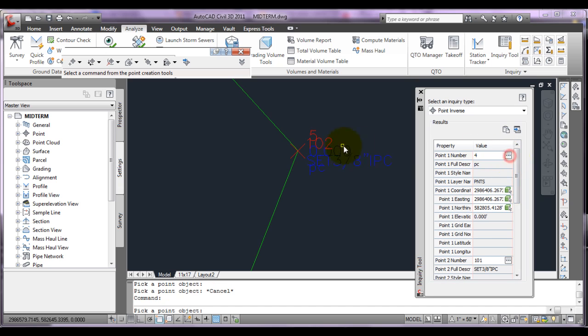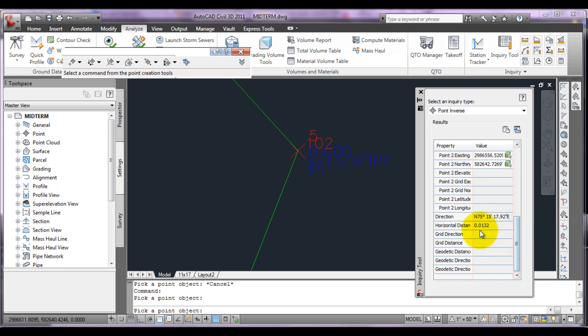And the reason why I do this is to make sure that there's a check and balance on that point set in the field. Make sure that they set it within your allowable standards. And that was 100, which is still fine. So you want to make sure that it's set within the allowable standards, and positional tolerance is okay on those. And it's just a quick way to check that. Before you start drawing the plat, you want to make sure there's not any other problems on the survey.